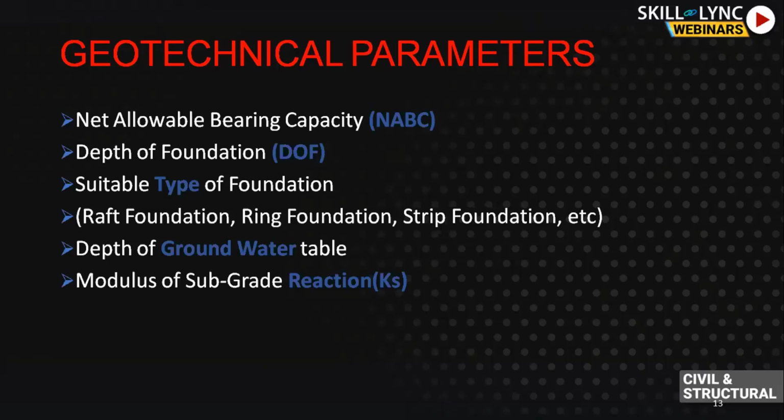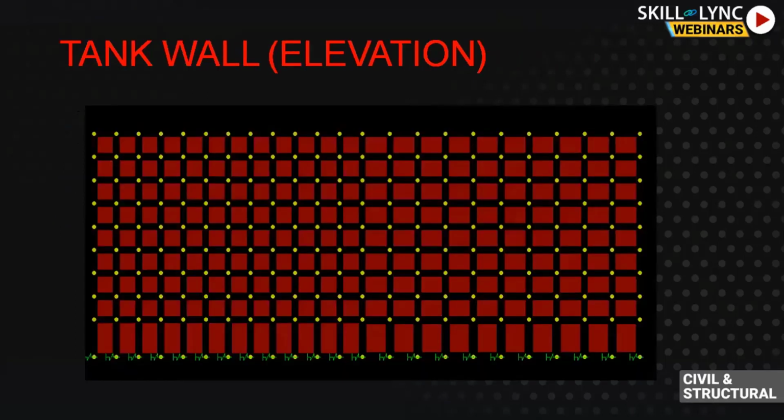Now, going back to the previous slides, the springs that I have assigned, I have taken these values from the geotechnical report. In Foundation Analysis and Design by the famous Joseph E. Bowles, for the bearing capacity, you multiply it by 4, and with a factor of safety of 3, we get the area springs we apply for isolated footings. And if you multiply it by 90, this is a general practical rule of thumb, 90 times net allowable bearing capacity is your area spring value.